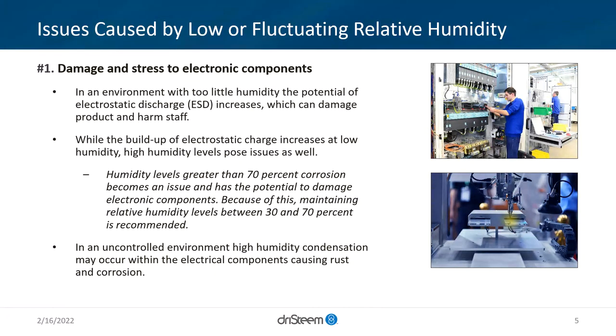So it's a really broad range. Just like that, human occupancy is different than that process range given. So if we talk about human health, 40 to 60% RH, okay, so now we're starting to narrow that scope. This is just one aspect of what that final RH percentage set point may be.